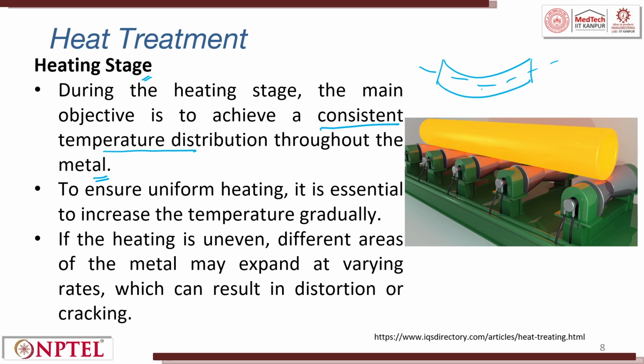If the heating is uneven, different areas of the metal may expand at varying rates, which will try to either distort or crack. When the gradient is very steep, there can be cracks and distortions. So, for uniform heating, it is essential to increase the temperature gradually.